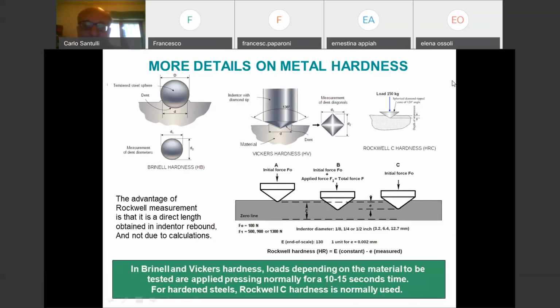It's a very fast test, the metal hardness, and also for plastics and so on. It's very interesting doing hardness. Why? To make clear the fact that hardness seems quite imprecise, and in fact, in some cases, it might be imprecise. What is the difference between a tensile test, say, or a compression test, and hardness, is that tensile and compression tests are made on samples.